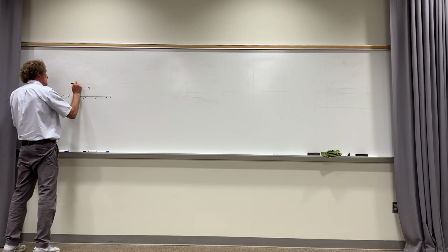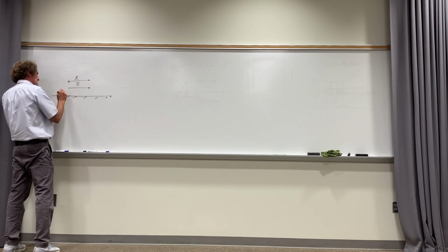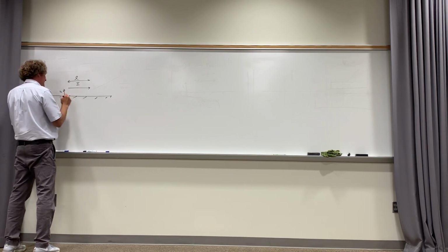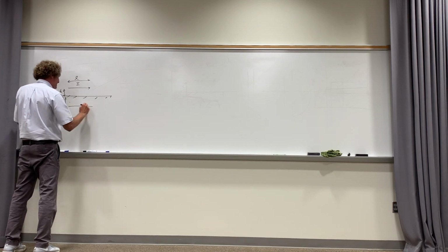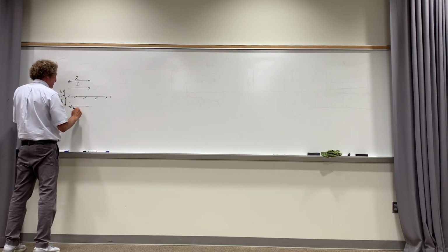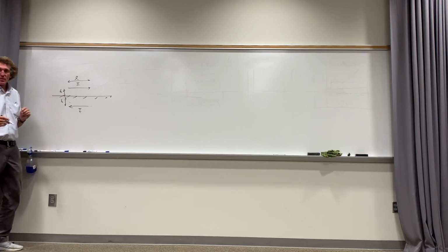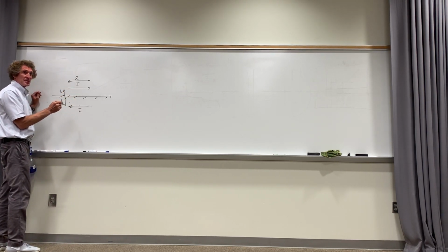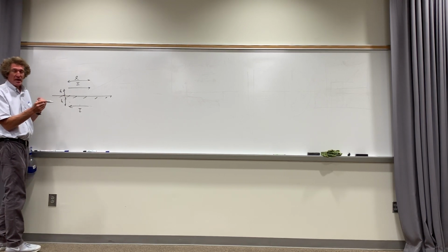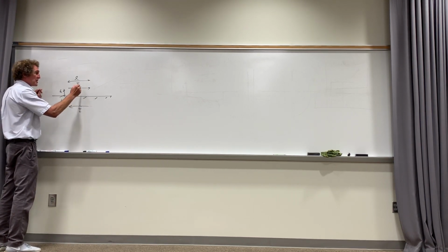Now, if you have a current I like this of length L, and it's at a height H, and it images in the opposite direction at a height below that H, you can see one thing happening. Now, the electric fields from these two don't add directly, because you have a phase difference, right?